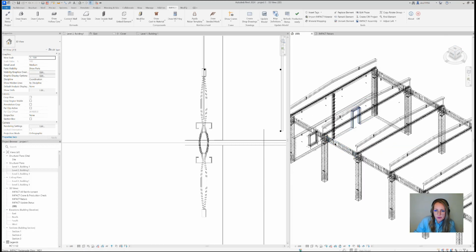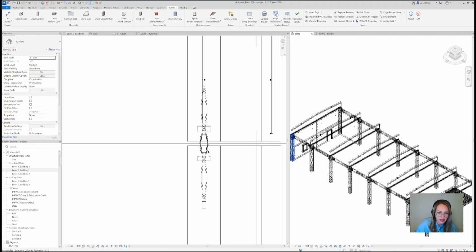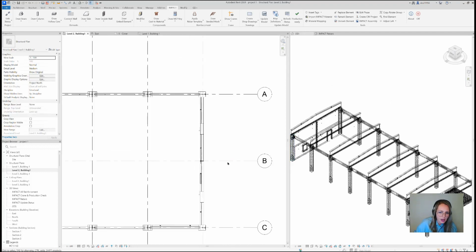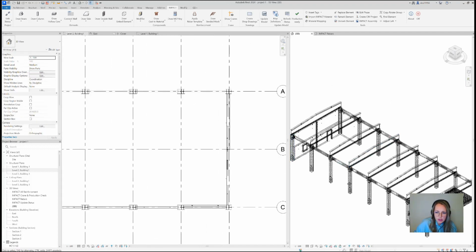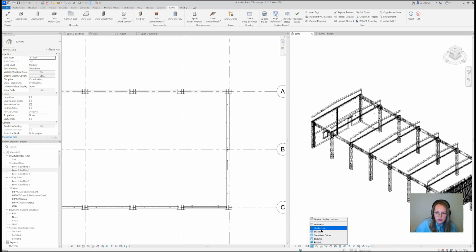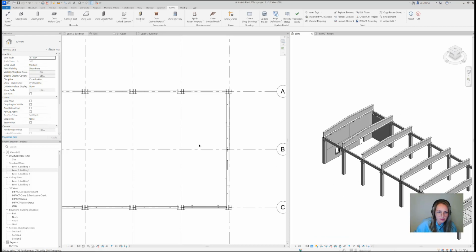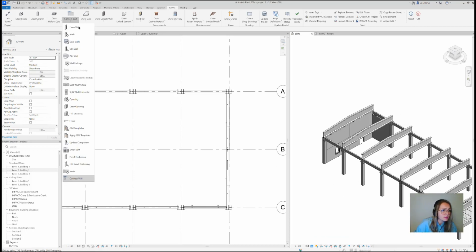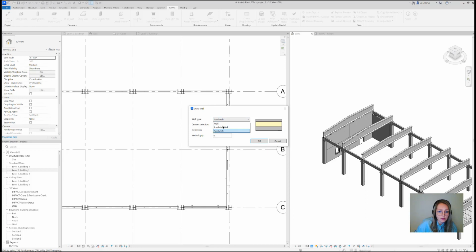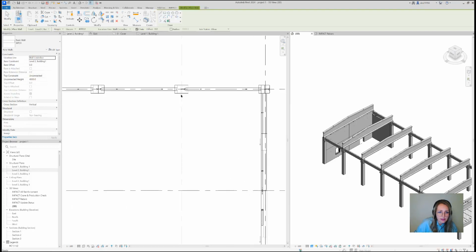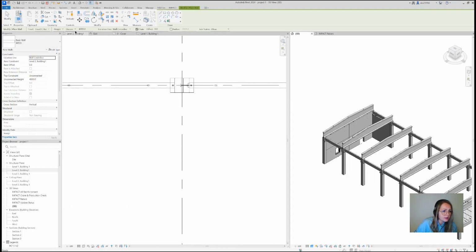Okay, what we're doing now is we're going to do some solid walls, panel thickenings, and slabs on top. So let's get moving. I'm going to do some solid walls, and in order to do a solid wall, you need to use again the draw wall command. And I'm going to say draw wall and use the wall. I have a definition for that. No gap intentionally again.